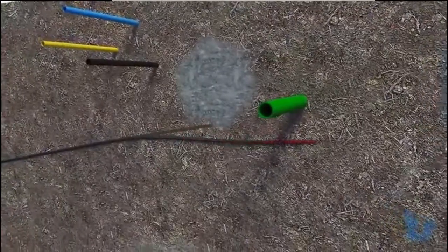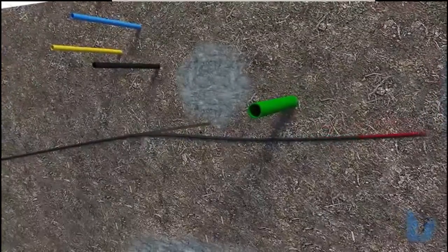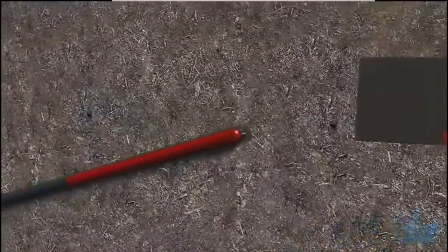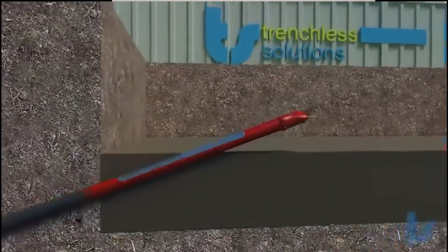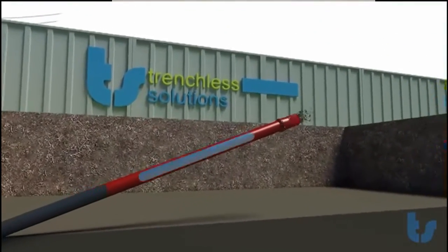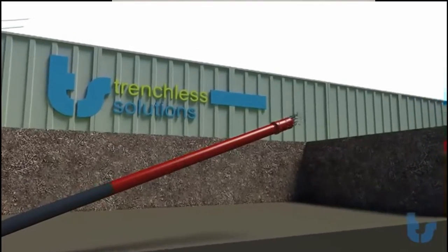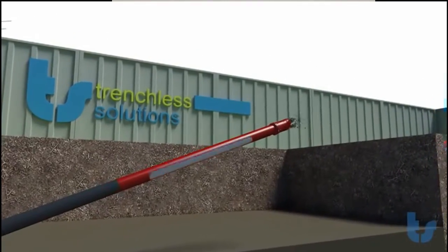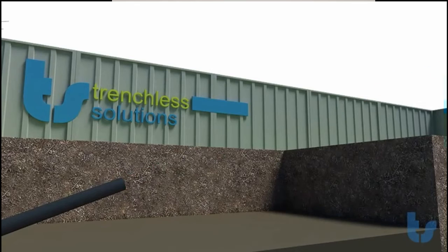They're coming now. They're going to hit a green pipe, so now they're going to stop. They're going to stop the drill rod at 6 o'clock, and then they're going to push straight. That's going to cause the drill rod to dive, and then they can start re-drilling again. So that's how they control the drill rod, and they can get accuracies of about 50 millimeters or better.